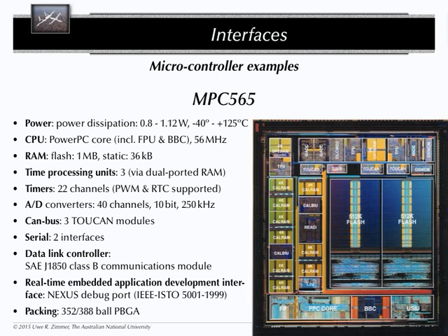The classical debugging way, GDB, or whatever your favorite debugging environment is, of course complete rubbish for those kind of environments, because if you use those kind of debuggers, you assume that you basically have a sequential system and it makes sense to actually stop it. Now, stopping the CPU here and everything else around is still running doesn't give you any sensible information. Plus, it is mostly used in a real-time environment, which means you cannot stop it in a sensible way.